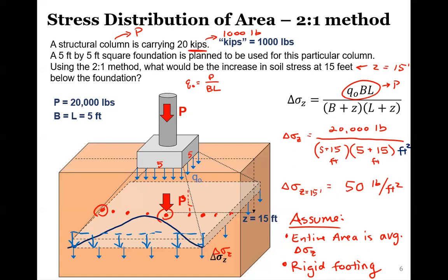So this is still a kind of deeper phenomenon in geotechniques, but this technique again assumes that this is a rigid footing, where a lot of times our theories, like the Boussinesq theory, are all derived based off of a flexible footing because it's a little bit more realistic.